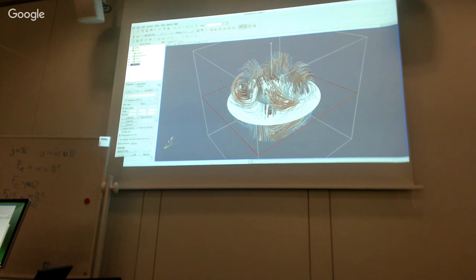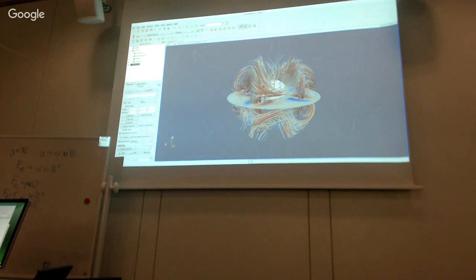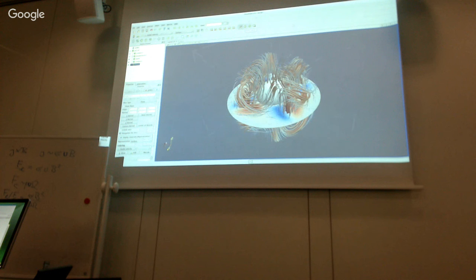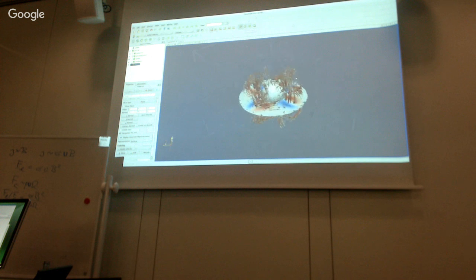Okay. So what do I want to display here? So what do I want to display in this plane? I don't know, radial velocity, whatever. And I don't want to show the plane, which is just useful for plotting at the beginning. Right. Show center. Okay. Well, and then you can put some transparency, some fancy stuff if you want. So, well, that's about it. So those are the three tools you may want to use: slices, contours, and streamlines.